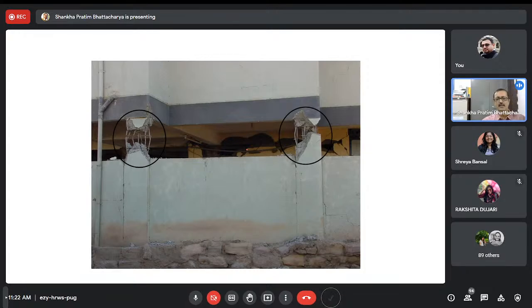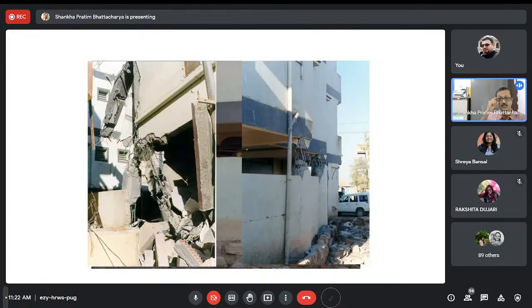So what is the remedy? From the remedial point of view, our engineers should also check the condition of the short column. If it acts as a short column, it should also be prepared for that. The new earthquake code has given some kind of formula for checking whether this particular column, yes, you design it as a long column, fine, but can also be protected against that kind of crushing under the compression load or not. See, this is the failure, short column failure, Bhuj earthquake.